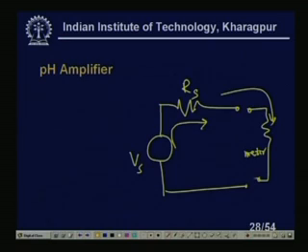So, the basic characteristics of the pH amplifier is that it should first of all be a DC amplifier, and amplifier means it is amplifying and also measuring the voltage output of the pH probe, which is coming from the reference and the measuring electrode, because 2 electrodes are there, okay. If I take separately, 2 electrodes are there, so this voltage is to be measured between this point and this point, right. If it is combined also it is the same thing, because as I have seen, the 2 electrode leads are coming out even in the combined electrodes.